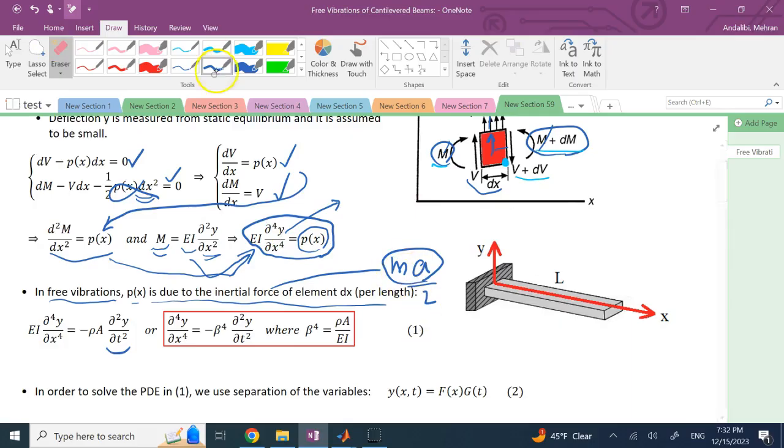the question is, what is m over L, where m is rho, the mass density, times volume V. And volume, you know, is equal to cross-section A times length. So if you divide by length, this term here is going to be what? It's going to be rho times A times acceleration. And that's what you can see here. Rho times A times acceleration. The only other thing we have is a negative sign.